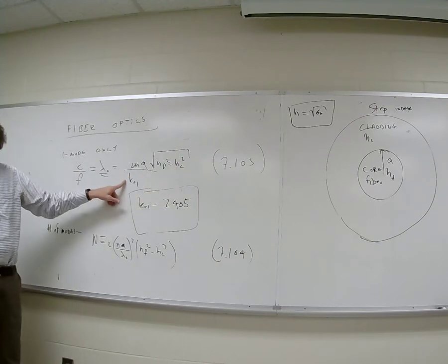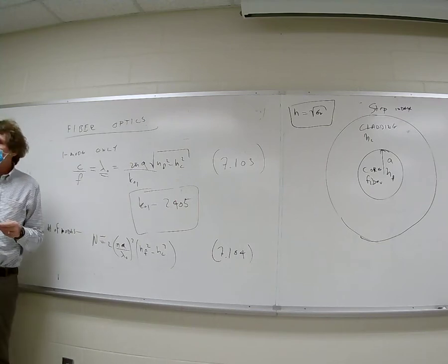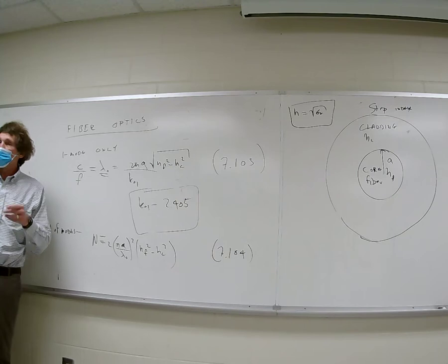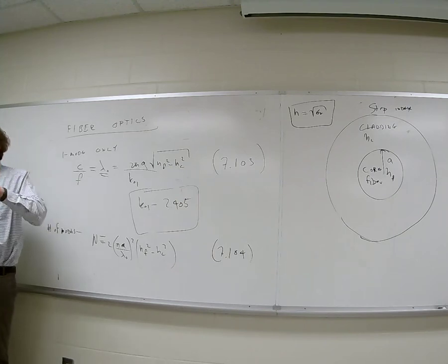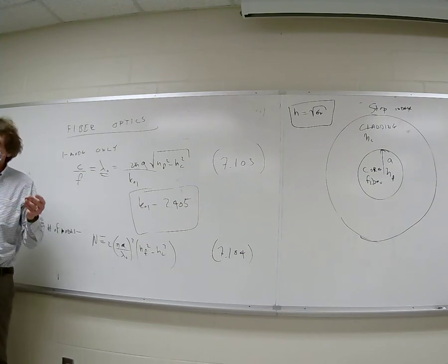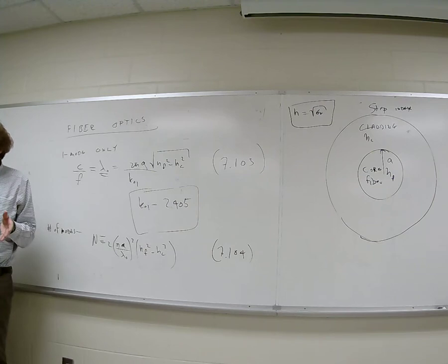We know K01 is a Bessel number that has to do with the solution of Bessel's equation. I try to give you a little insight in Bessel equations. When you do the del squared operator, del squared V plus K squared, or plus beta squared times E equals 0, in cylindrical coordinates, when you separate out variables, the variable that's actually in the radial direction is a Bessel equation. The solutions to that are not sines and cosines or exponentials. They're called Bessel functions, the first kind, second kind, things like that. Did y'all take a look at that? At least expose yourself to the terminology.